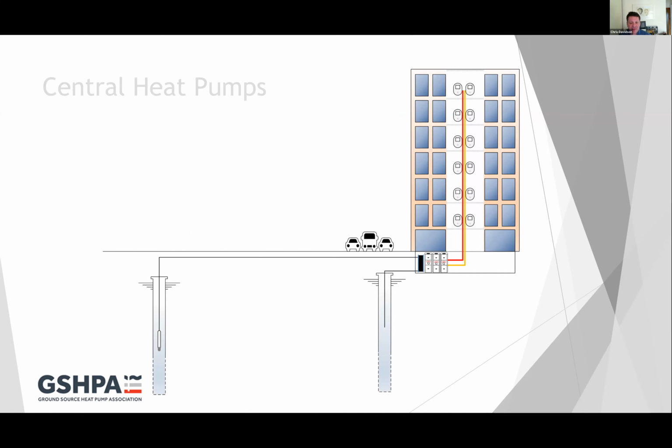You've then got decisions to make as to how you deploy your heat pumps themselves. So for example, this is a central plant solution. You can see the water wells here feeding the heat exchanger. Then the heat exchanger keeping an internal closed loop which feeds the heat pumps. And in this instance, we've now got a high temperature distribution system up through the building to heat interface units, for example, in an apartment like this.